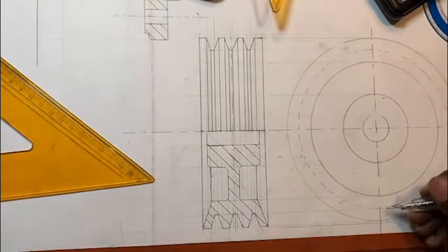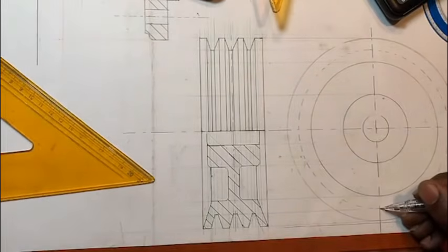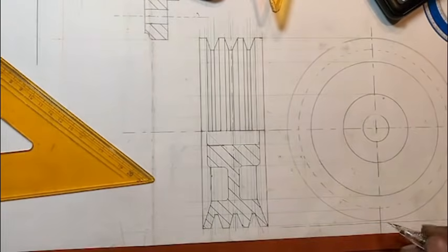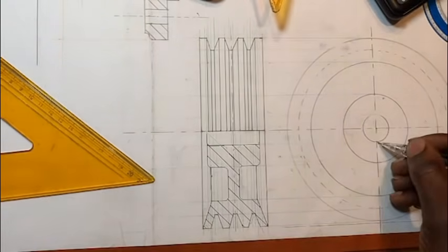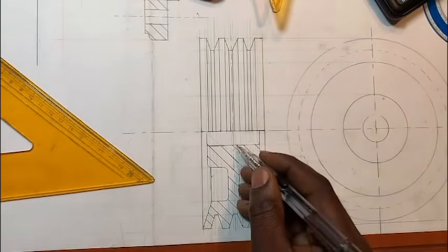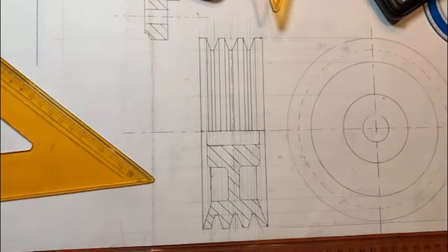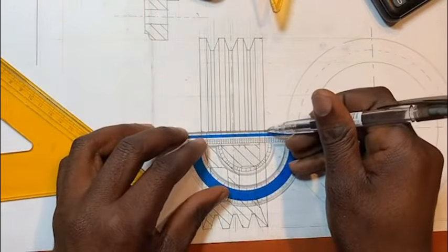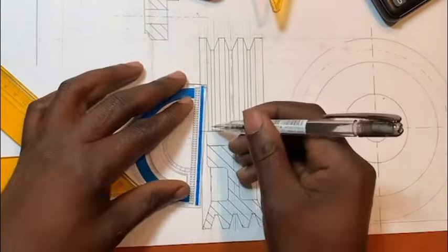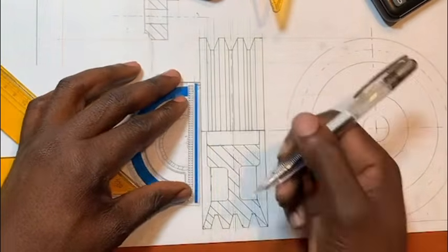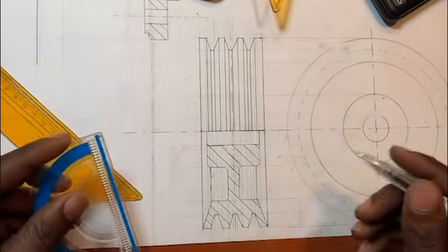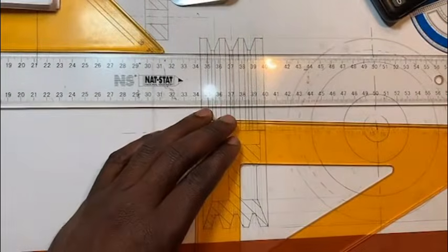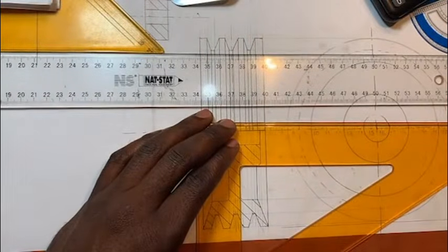Because the hacksaw started to cut from here till here, it didn't cut this one, but the other part it cut. So from here till here is the hole. We cannot have hatches here. You get what I'm trying to say? So I can fix it nicely. The bottom part in sectioning. That's how it's supposed to look, my brother.